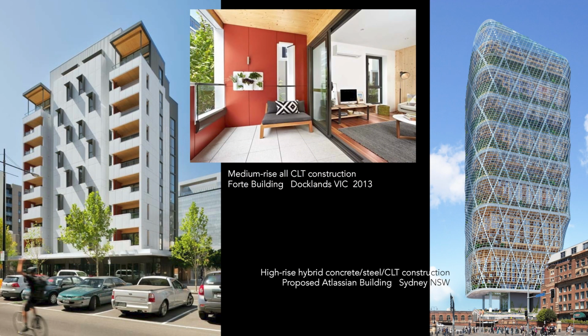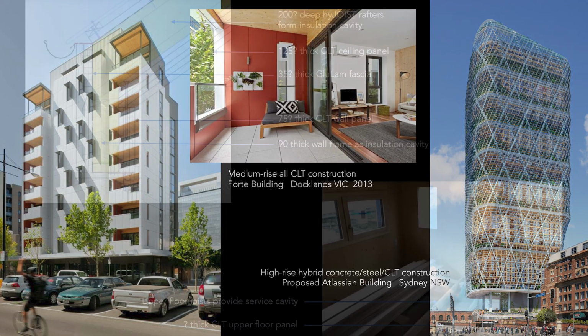Quickly to illustrate, just on designing lean with materials, for medium-rise construction, say 5 to 15 floors in height, cross-laminated timber from fast-grown plantation wood can make for a carbon-friendly and material-efficient structural system. But for low and high-rise, where it also seems to now be the rage amongst architects, CLT is likely to be wasteful of precious wood resource.